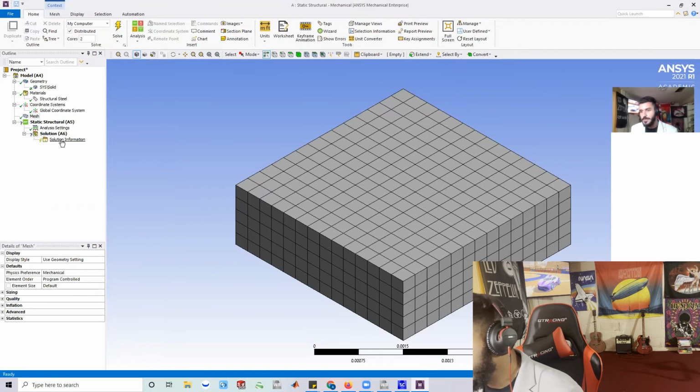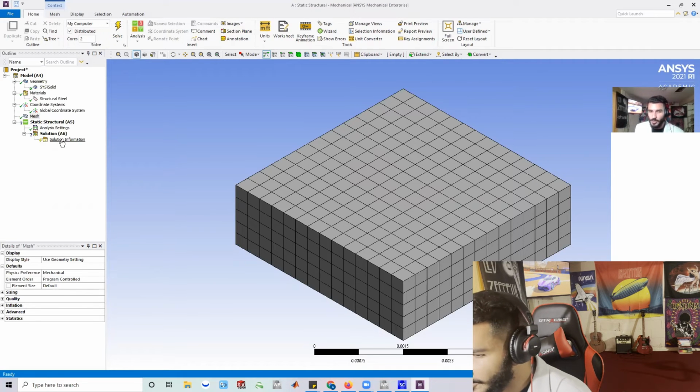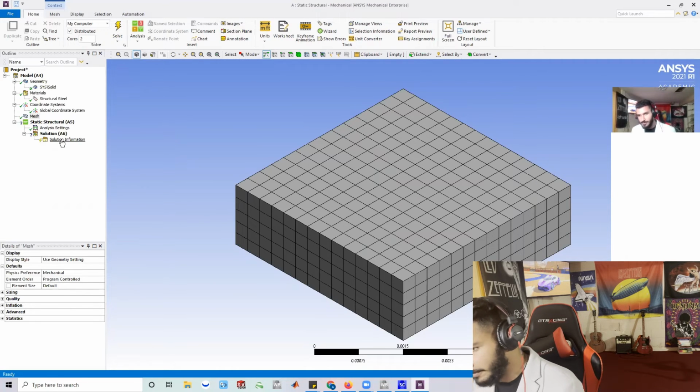Now, since it sounds really nice to just make your squares as small as possible and get very accurate results, can someone tell me what the downside to that is? Takes more computational power the more detail you want to do. Right, exactly. Because I am making my squares smaller and I'm making my simulator do more math, I'm requiring more computational power.